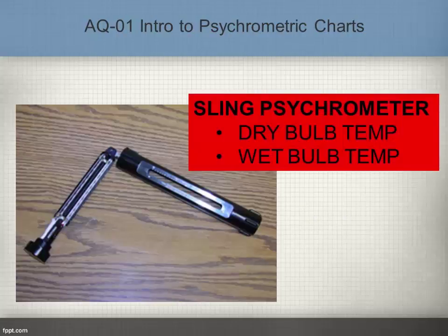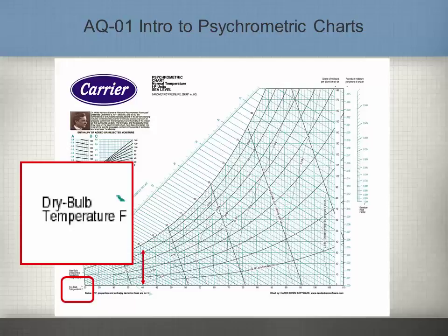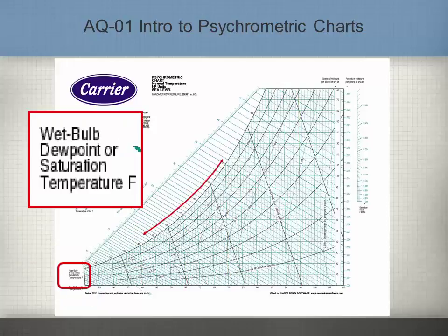In measuring air quality, the psychrometer is frequently used and results applied to the psychrometric chart. The psychrometer measures only the dry and the wet bulb temperature of the air mass. By plotting the dry bulb temperature on its vertical scale and the wet bulb temperature on its diagonal scale, we can determine the other 5 values of air quality from the point of intersection.